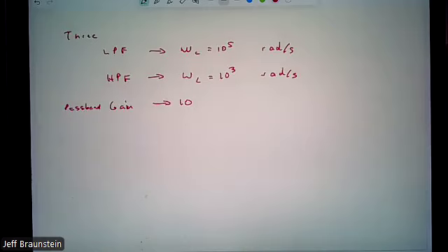You don't need second order circuits here. It should be a first order circuit, because that was part of the spec that we put forward. Second order circuits give you a better stop band, so ultimately you might want that, but it's not part of the design process here. Does that make sense?